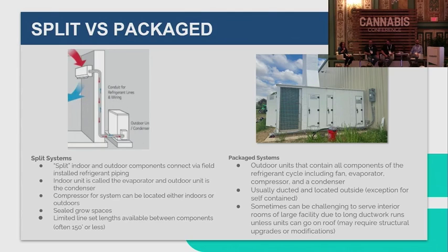The maintenance can be a little more intense for a split system versus a packaged, but the packaged system, alternately, is all outside. A lot of times people just have a preference about not having equipment in the room, so those can just be ducted in with a single airstream, or even add some standalone dehumidification to reduce that ductwork sizing a little bit.